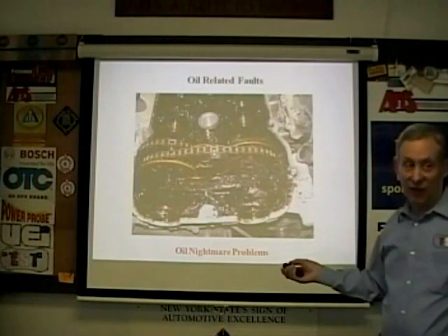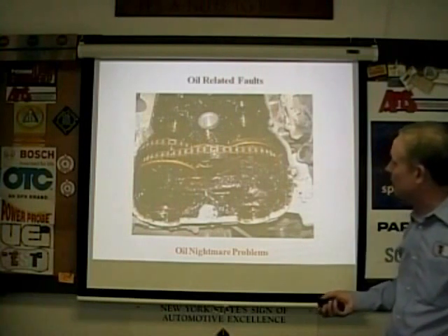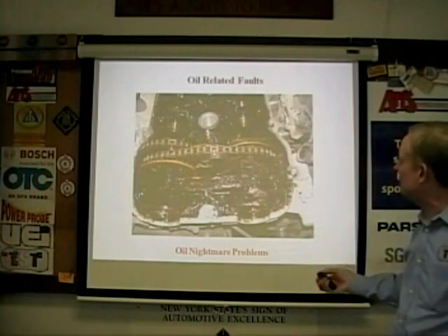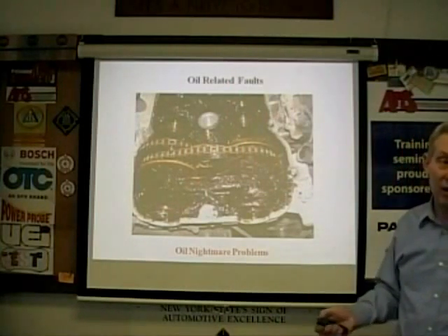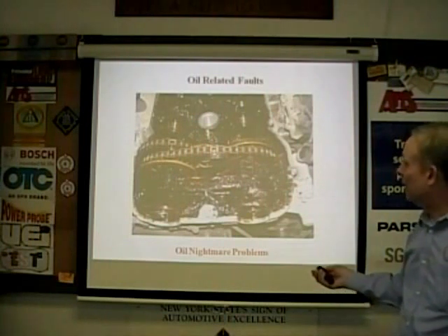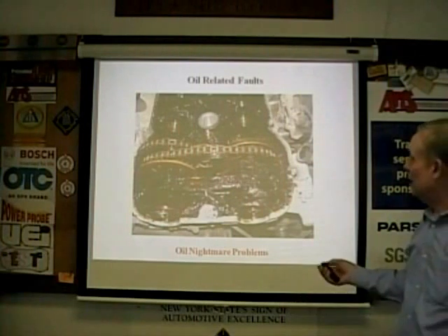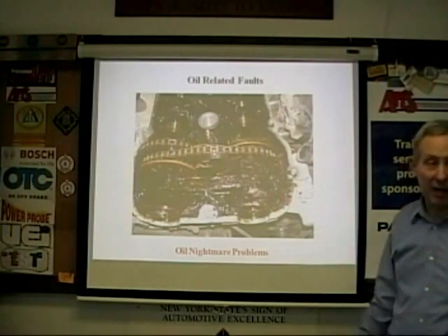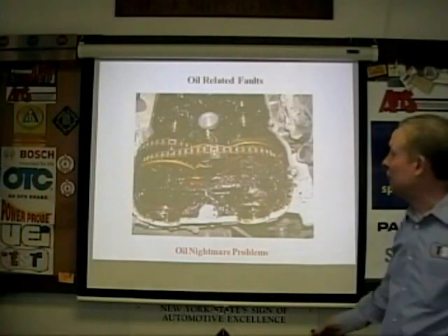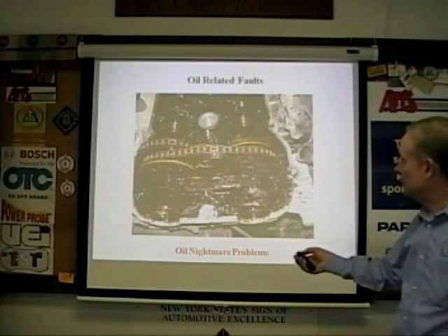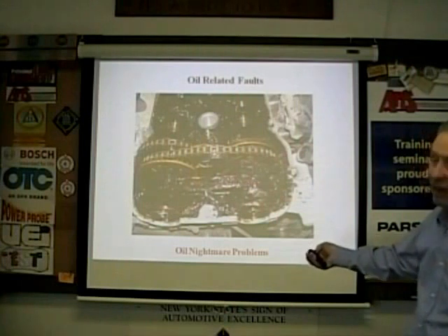There's actually a lot of different generations of Vanos. This particular Vanos, which would have been a mid-90s, late 90s version, would usually not actually chatter. What it would have, however, would be codes for cam advance. It might have a power problem. Sometimes they had a misfire problem if they hung in the advanced direction. Earlier generations than this had a different layout inside the Vanos.